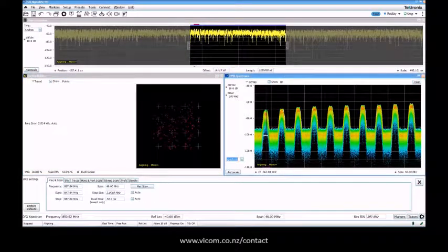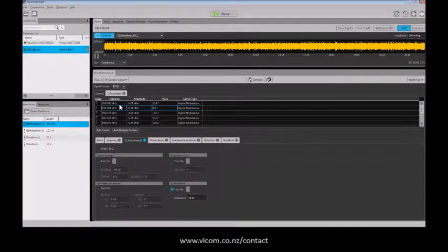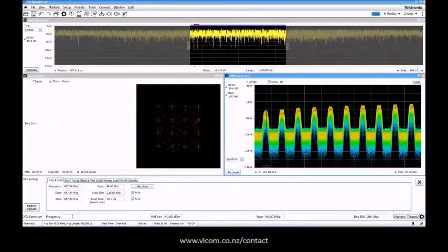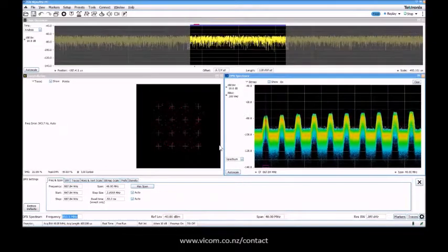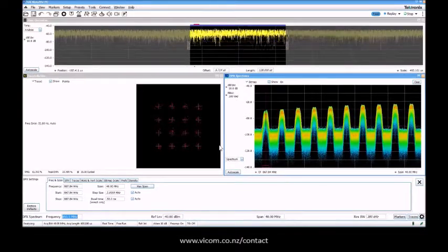Hopefully, and what was the center frequency? It was 850, 50 meg or something. Was it 851 or? Let me see if I can get this. QAM 16 is a little bit more of a... You need to know the frequency. If I look at this again, 850.5 is the one. So 850.5 megahertz is the actual channel, and here you go. You can see it. Now the antenna is a little bit moving around, and you can see it's not the best, but this is an antenna measurement. Okay, so this is a stable signal.